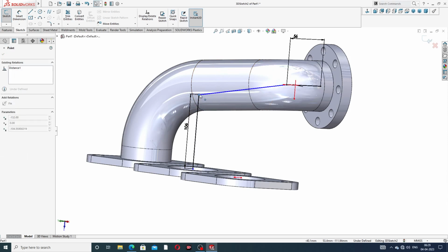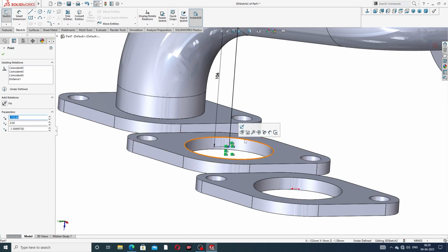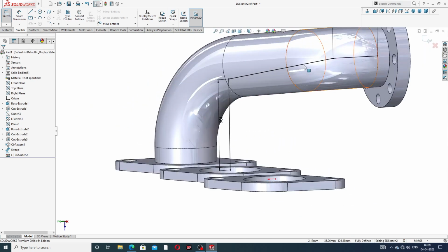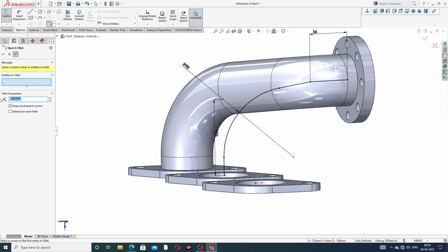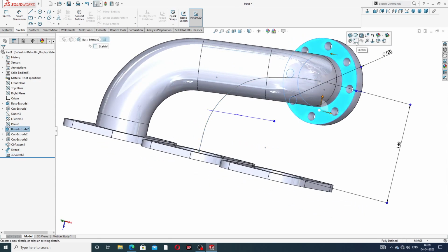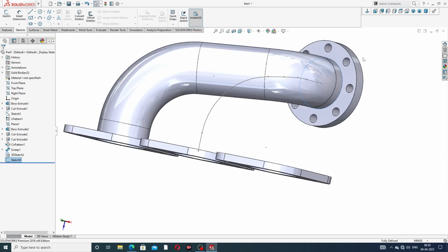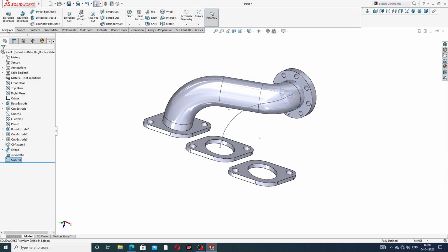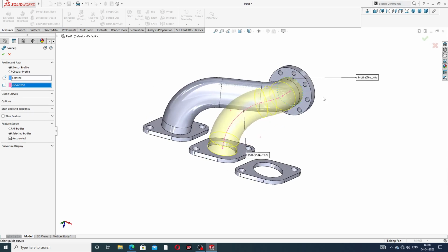connect to this, okay, this is perfect, okay, and use a fillet of 96 millimeter, connect to this, and 68 millimeter fillet is this point to this, okay, this is okay, and this path is also drawn, and this exit, and again select this sketch, and drawing again select this, and use convert entities and exit, both are okay, this profile and path are drawn here, and again use swept boss base, automatically the profile is selected here, and this use the path is this, okay, this is perfect, and click okay,